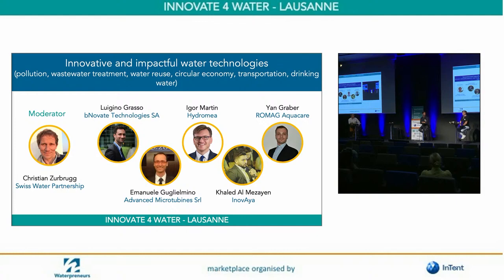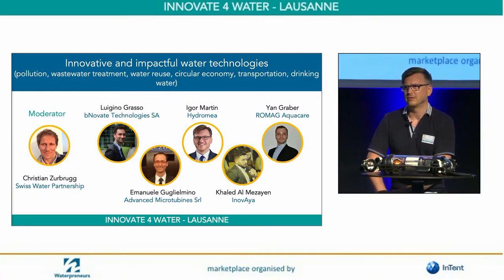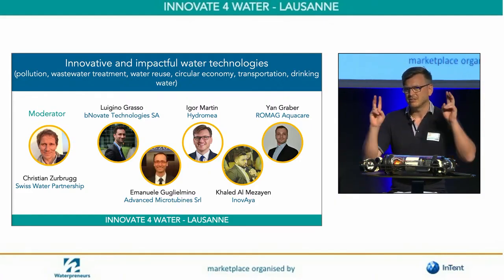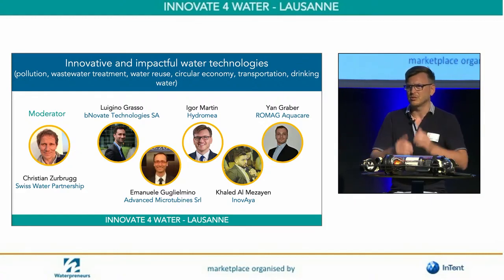So our initial payload is visual. We have a pretty sophisticated camera system and lighting system to just identify the problem areas. We also plan to add a UT sensor for corrosion measurements to measure the metal thickness. And then it really depends on the necessity of a particular application. The beauty is that we're not building just a drone, we have a platform, so we can relatively easily put things together for a particular application to address those inspection needs.